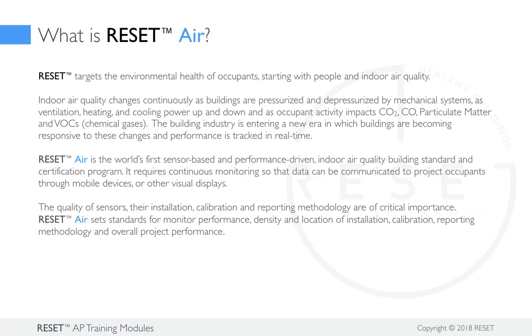Reset is targeting the environmental health of occupants, starting with the people and indoor air quality. Indoor air quality changes continuously. And this is really important for everyone to understand. Spaces are dynamic, and what we're really trying to look for are the impacts of CO2, CO, particulate matter, and VOCs, which is your chemical off-gassing.